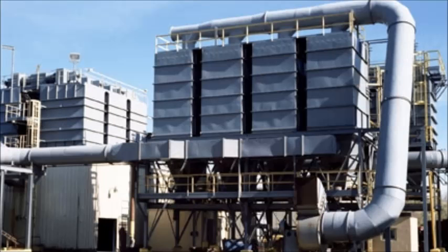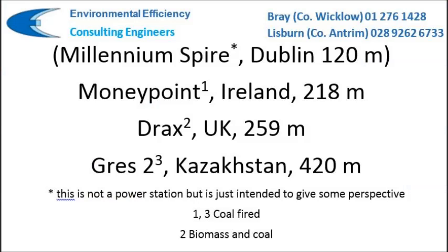So, what can you do if the results of the air dispersion model are not favourable? The most sustainable approach would be to see if the amount of pollutants emitted by the stack can be reduced, perhaps by changing the process or raw materials. Less sustainable options include installing abatement equipment, such as bag filters for particulates or scrubbers for acids and alkalis. Probably the least sustainable option is to raise the stack height. This will disperse the pollutants over a wider area.